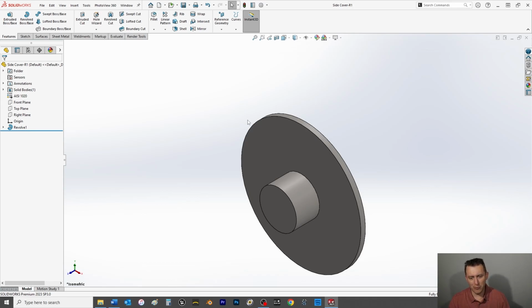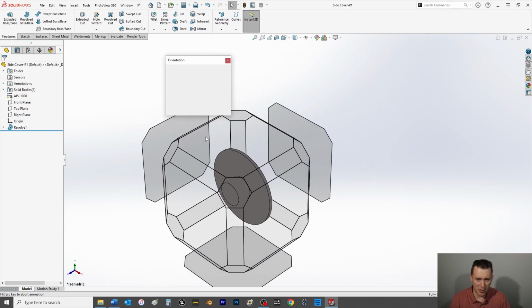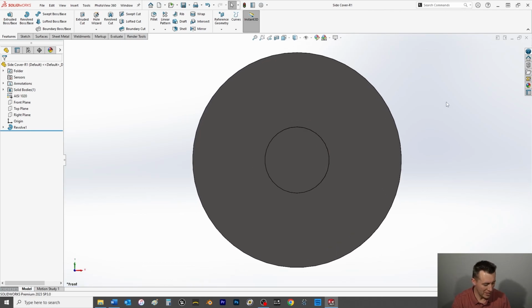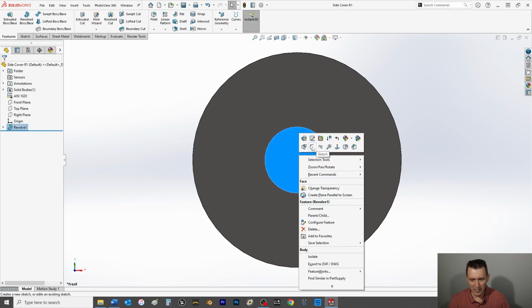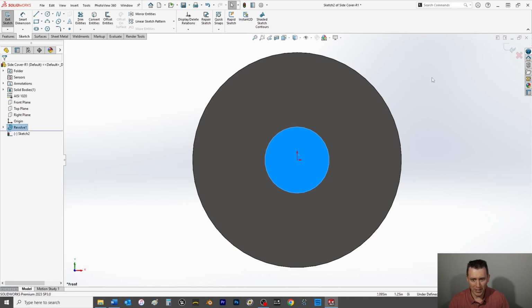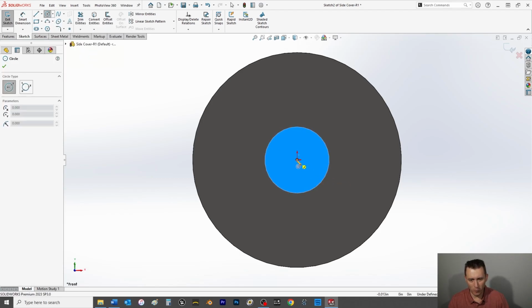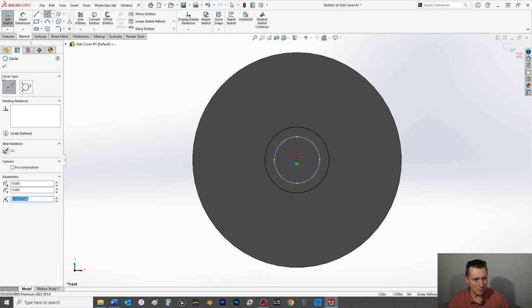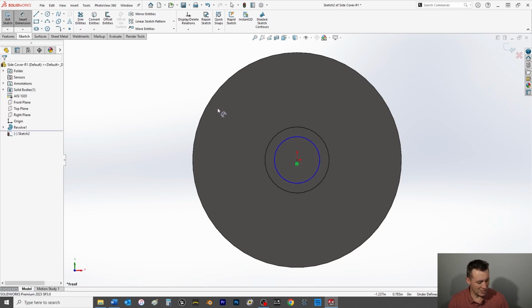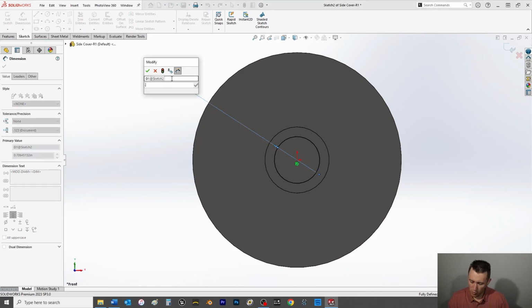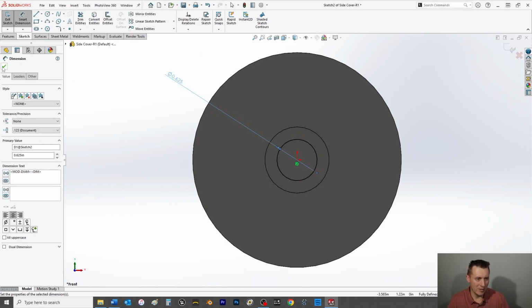And now section 3.11, page 123, we're going to hit the space bar to bring the front plane normal to. And from here we're going to take the frontmost plane, which is this circle here. We're going to right click and make sure we choose Sketch. Then we are now automatically brought into the Sketch tab up here. We will choose a circle with a center point. We're going to choose the origin, coincident to that, for the center point of the circle. Click drag out. Click OK, and we're going to give that a smart dimension of 0.625. And then we're going to click OK.